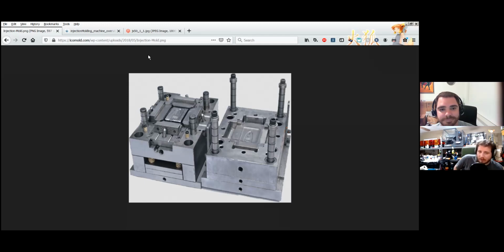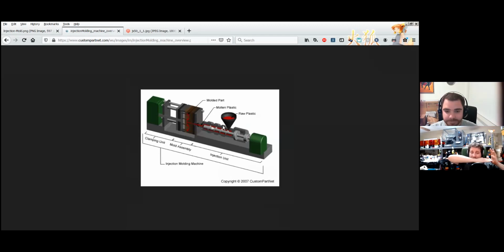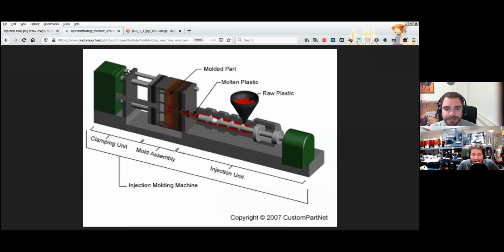These machines generally use Archimedes screws, and I think that's going to bring us into your next image. It's just a big corkscrew where you have hot plastic and it's slowly forcing it in. And it's going to do that with a fair bit of force too, because you want to fill up and make sure there are no air pockets, because that is kind of the issue.